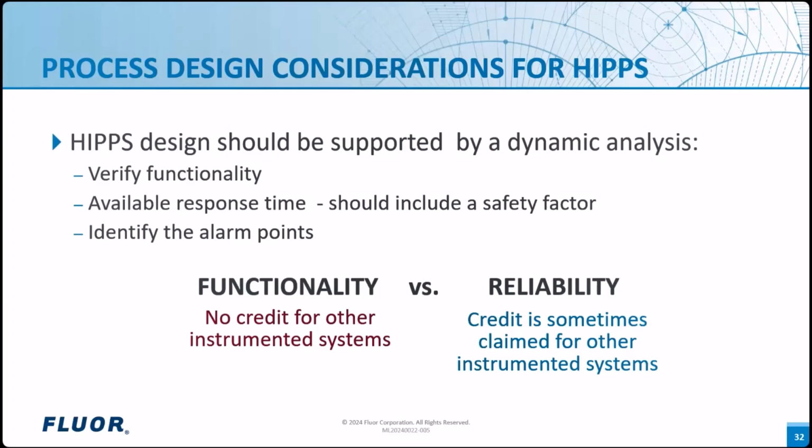For the initiating variables, it is sometimes assumed that they must be pressure. Other variables may be more suitable to function as initiators, as we will see in the following example. A well-designed HIPPS can be rendered ineffective if the installed elements do not meet the required specifications. This can occur, for example, during a spare check or during field replacements of an initiator or final element. It's strongly recommended to document these critical performance requirements on the individual data sheets.